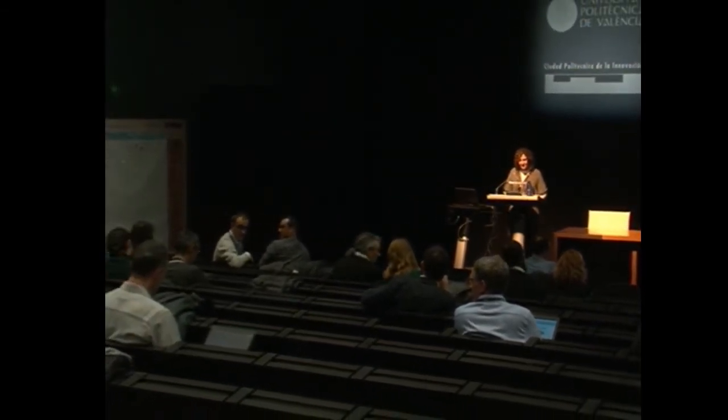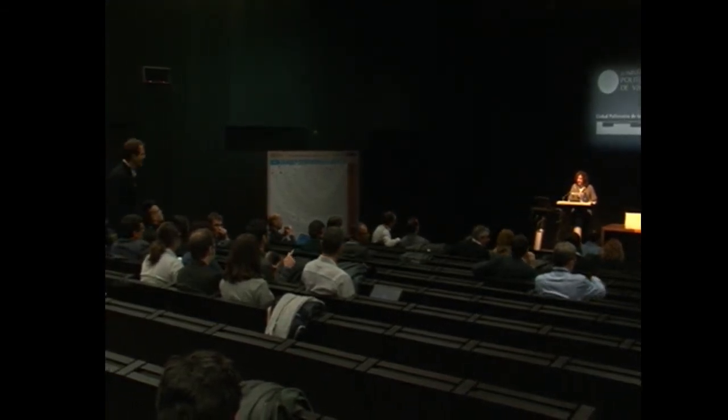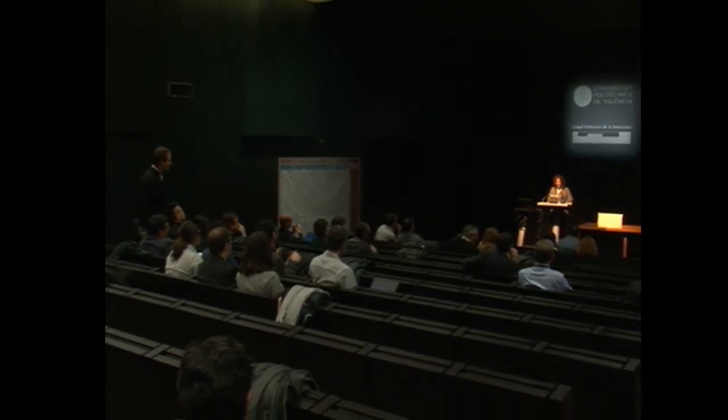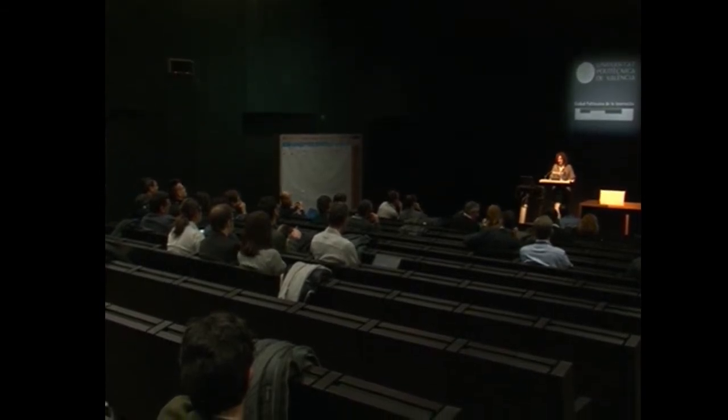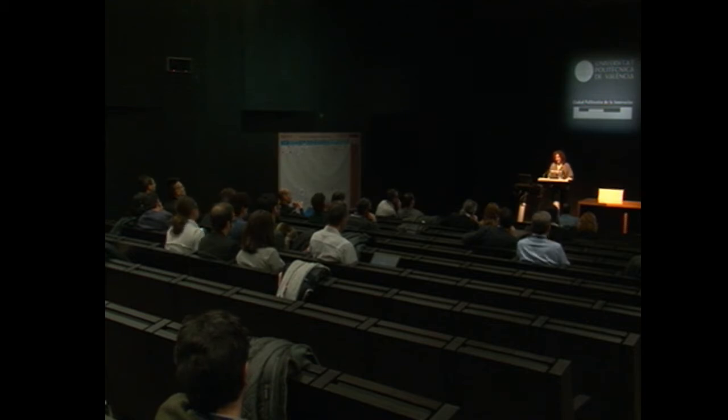Hi, thank you for your presentation. I have one question. What is the thickest film you can deposit, and how good is the film quality? In which layer? I mean the silicon nitride. Okay, I think the silicon nitride, I can grow a process with 600 nanometers. And I think the homogeneity is also 5%, like you see now. But I think the problem is that the higher you grow the silicon nitride, the stress is bigger. That's why I'm asking. Do you have any process to control the stress, to compensate the stress?